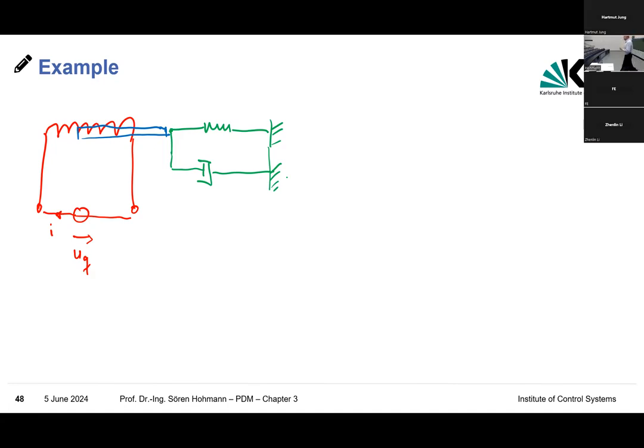Well, this system is sometimes called a voice coil system. Why? Because it operates like a loudspeaker, similar to that voice coil. It's one famous thing which helps to do nano positioning. Now think of, well, here there's some problem because you want to have a friction-free movement.